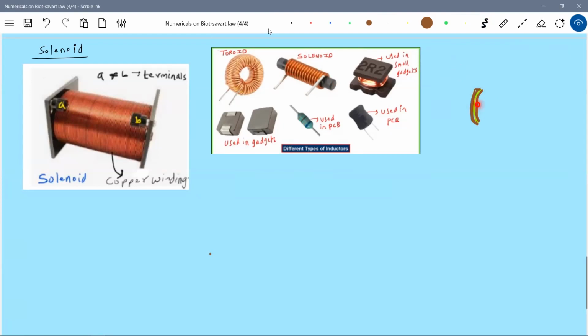So though these two turns are in contact, between them an insulating layer will come. Then again, I'll bring the insulating layer. Now actually they're in contact, but between them a liquid layer, an insulating layer, will be brought. Like that, they'll be very closely wound. If you look at the practical, you feel as if they're in contact, but in between there is a small liquid layer, I'll take a brush and just put it like this.